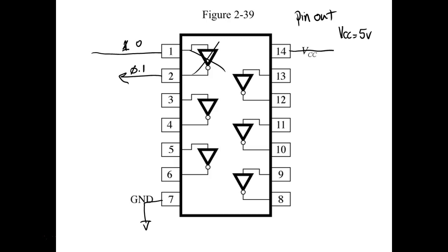So we can make an AND gate. Of course, if I put NAND gates, a 2-input AND gate would require how many pins? You said 2 pins? 3 pins, because you've got to have an output. And people don't understand that. So every gate, when we say a 2-input AND gate, that's going to identify the number of pins that's on the input. But we've always got to have a what? An output. And that's for the AND. An AND gate. This is the symbol. This is the symbol of an AND gate.